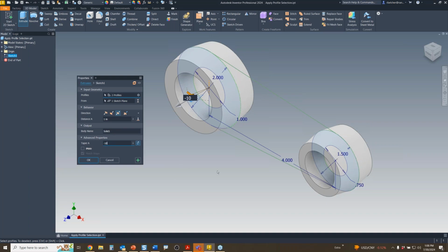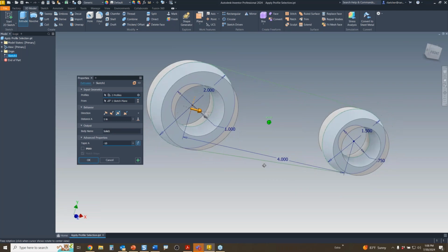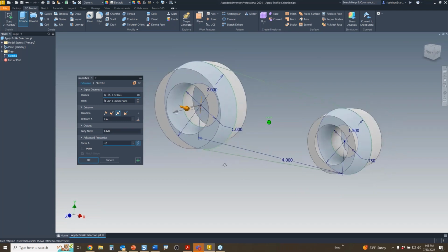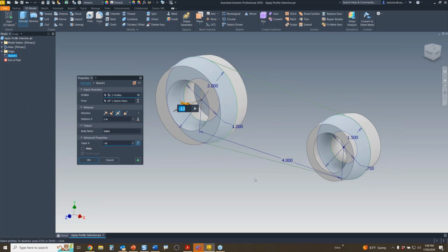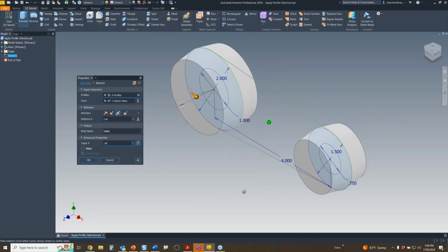But when you taper with this kind of boundary selection, I don't know if you can see it, but it's actually going to taper those holes right there. Well, okay, right in the midst of all this, I can hold the Shift button down, and I have to hold the Shift button down, to go in and reselect profiles. So that looks a little bit better for my very first feature. I think that one will work pretty good.